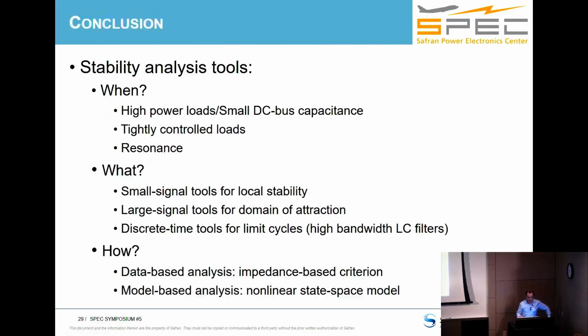And now the main conclusion. Three points. Stability analysis tools. When you have high power loads or small DC bus capacitance, you need to analyze the stability. When you have tightly controlled loads, they contribute a lot to instability. And because of resonance in LC filters, you have oscillations.